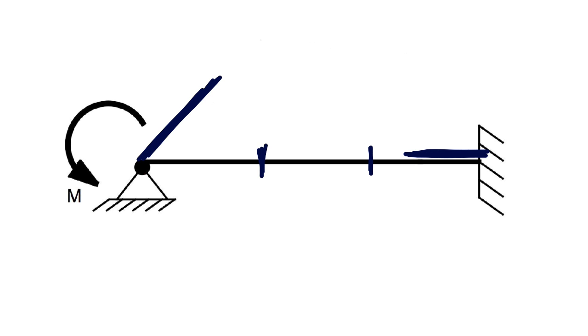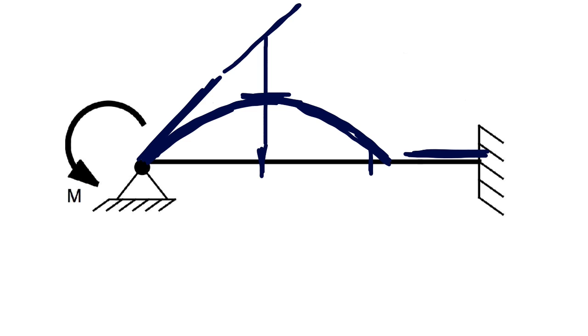Again, it turns out that the maximum should theoretically be at about 45% of the height of the extended line on the left. And we draw a small line at that height. Now, as before, we draw a rough arc curving downwards, starting tangent to the stub at the left end. We try to have the maximum height tangent to our horizontal height guide.